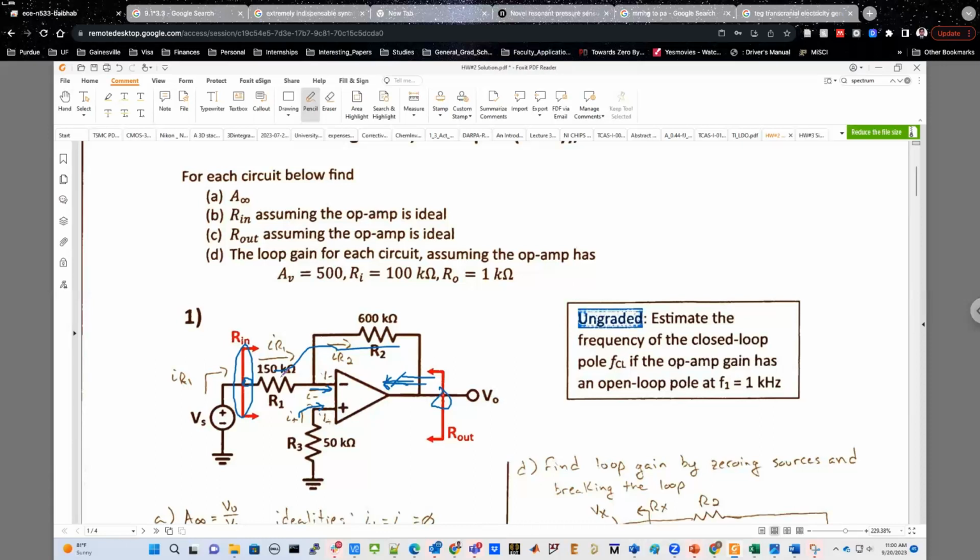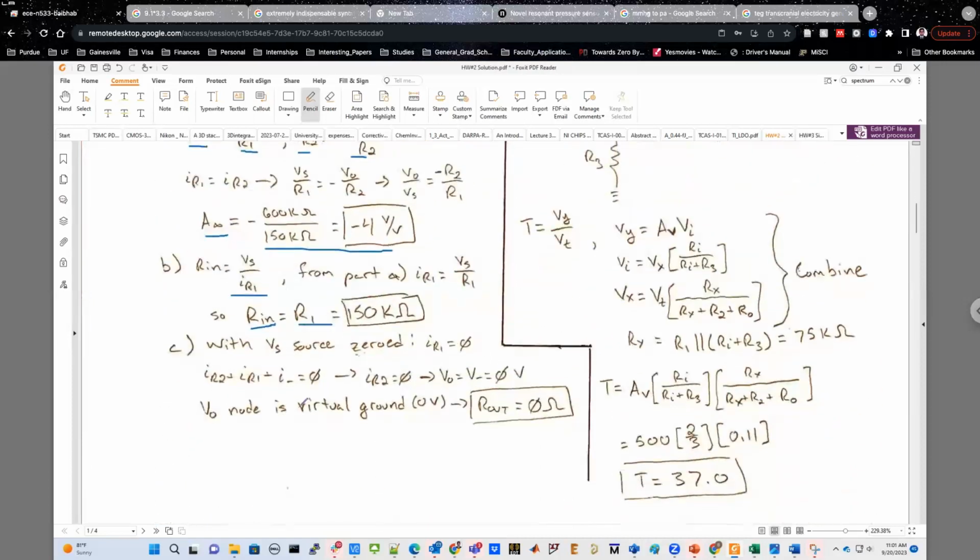So two resistances R1 and R2. The parallel equivalent of this, looking from this side or even that side, is R1 times R2 divided by R1 plus R2. And now we are saying one of them is equal to 0, so the numerator becomes 0, and the overall resistance becomes 0. Doesn't matter whatever the value of the other resistance is. So as you are looking into the op-amp, you see a 0 resistance, so whatever is connected in parallel to it does not matter. The overall resistance you'll see at the output will be equal to 0. So that's why your output resistance is equal to 0 ohms.